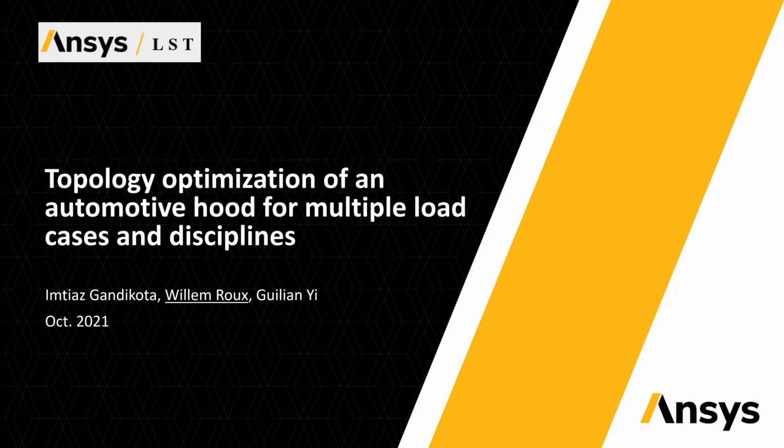We will be digging into several topics, firstly some theory, and then how to do the multidisciplinary optimization of this hood, designing it for NVH, statics, and crash. And then we're going to go to the design code. That's the pedestrian impact, that's the NCAP code. With all of those multiple load cases, we'll be doing a worst case design study to solve it for all of those many design load cases in the code.